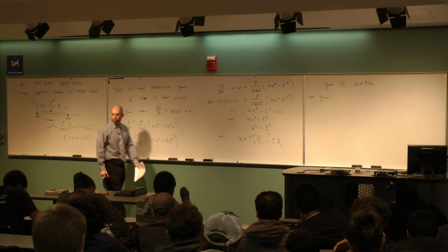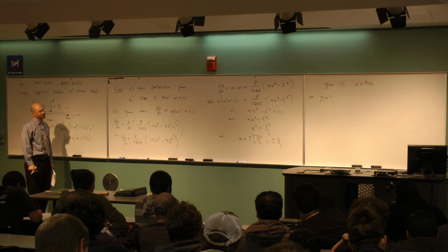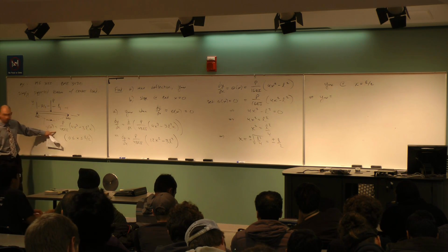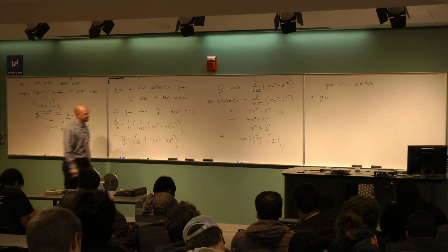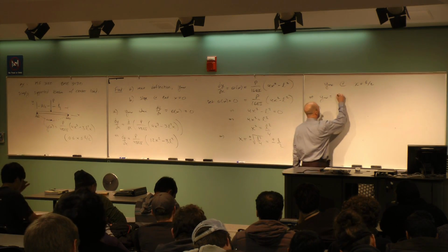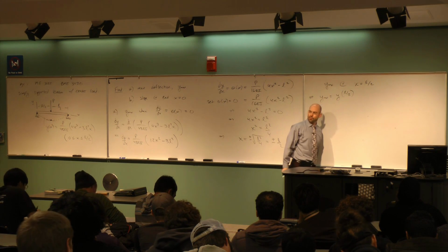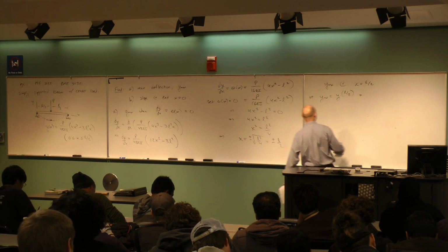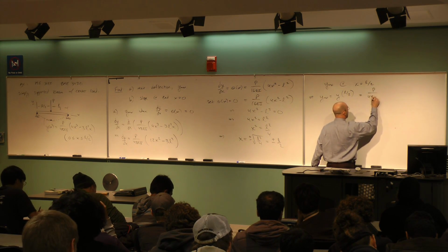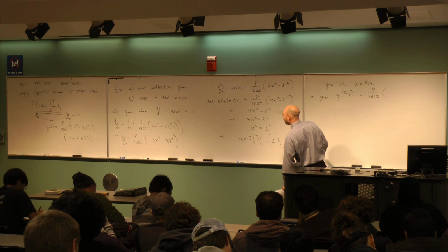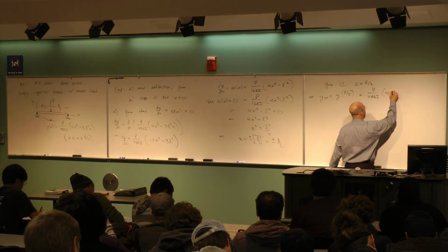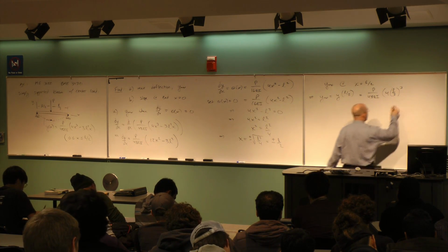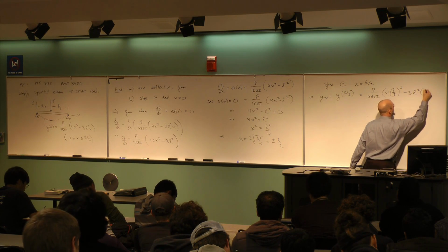I'm going to get the value by doing what? Substitute into the original equation, x is equal to what? Yeah, so I want y evaluated at L over 2, not multiplied by L over 2, evaluated. All right, and so what I'm going to get here is P over 48 EI. Okay, and I'm going to plug in an L over 2 wherever I see an x. So it's 4 times L over 2 cubed, and then minus 3L squared times L over 2.